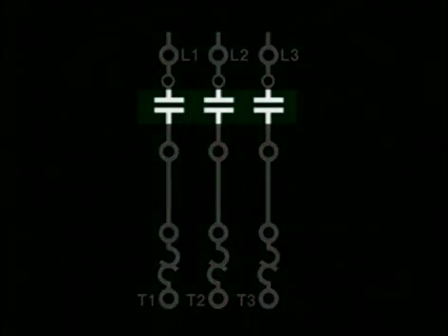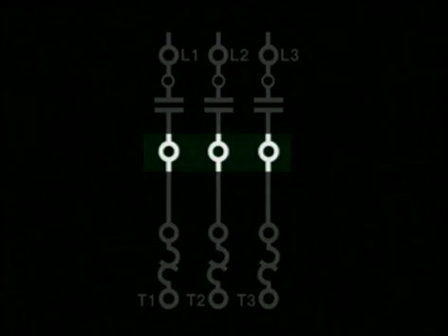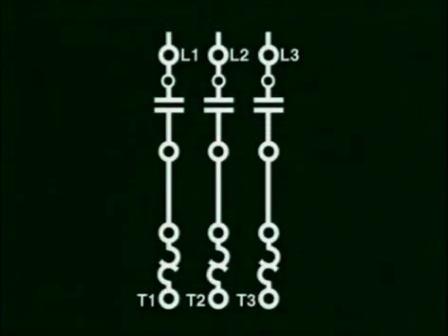Right below, we find the actual contacts that will turn the motor load on, and below we have another set of terminals which are normally used when we have reversing circuit connections. These can be considered power connecting terminals, as opposed to control circuit terminals. Under this second set of power terminals, we find the starter coil represented in the diagram in the middle cross-section, which is the location where you will find it in the starter.